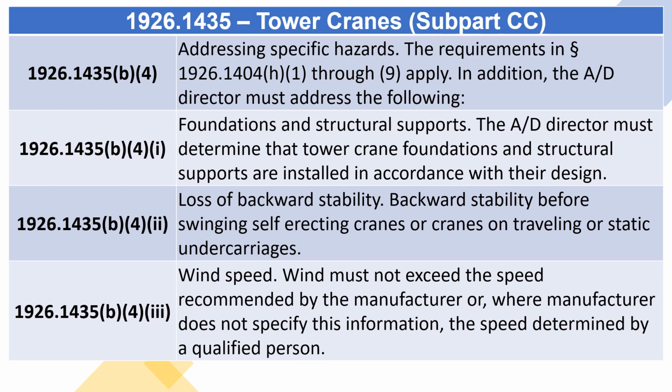Loss of backward stability. Backward stability before swinging self-erecting cranes or cranes on traveling or static undercarriages. Wind speed. Wind must not exceed the speed recommended by the manufacturer or, where the manufacturer does not specify this information, the speed determined by a qualified person.